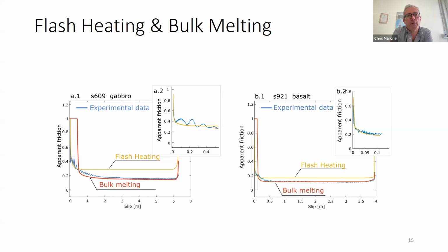Yeah, it's a really interesting point, John and Chiara, because you're generating heat, but of course you're always also losing heat, so your state variable would have to somehow bring both of those things together. And it makes me ask here, Chiara, in the model, what do you assume about the thickness of the zone that the heat is being pushed into? So the temperature goes up, it's always 200 microns thick? Is that what you said?